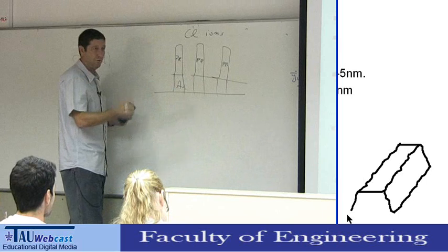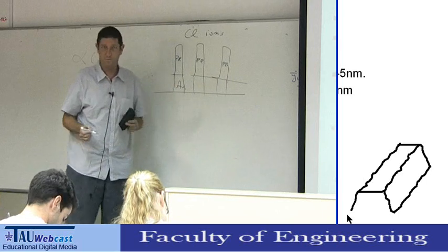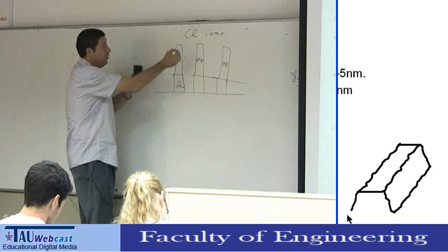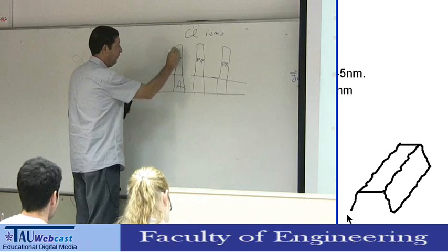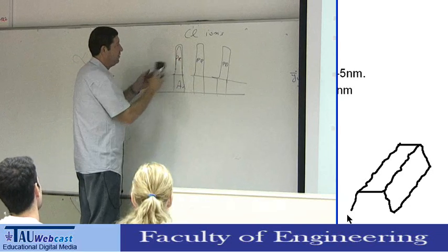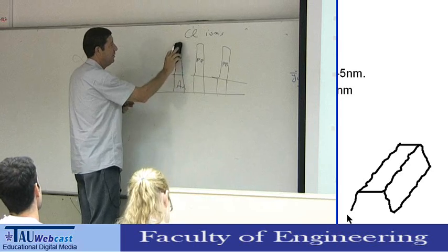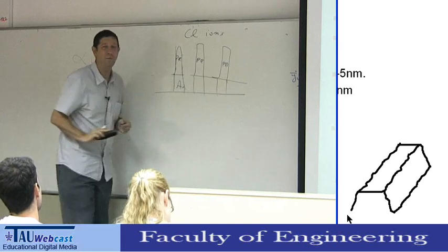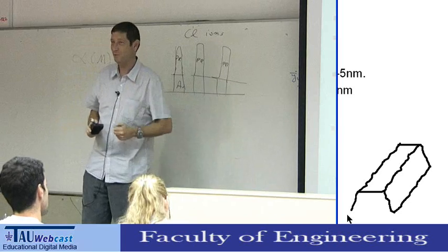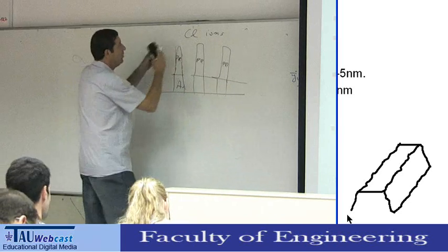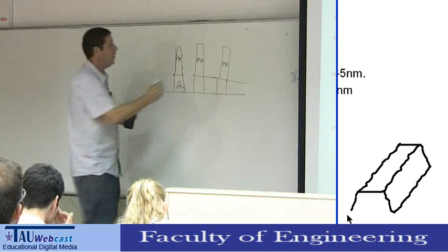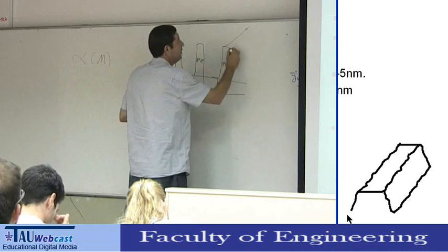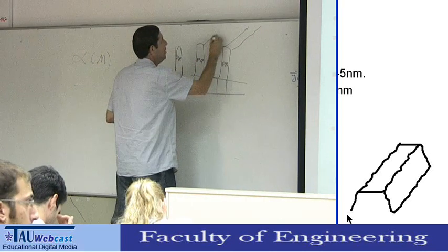Actually, during the process of the etching, you can have some photoresist erosion, because chlorine is a very corrosive gas. You also can affect your photoresist a little bit, so at the end of the process, it looks a little bit different than at the beginning of the process. But even worse, this is a 2D plot. In actual life, we have a 3-dimensional line.